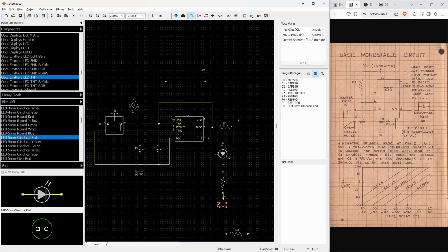So if I connect this to this, one interesting thing is if I click that, you can see they all highlight and it shows it with its net name ground. So that's important to tie those all together. I don't want this to just be a random other net, but actually connected to ground. So let's make the last connections here, going from out to the LED and the LED to its current limiting resistor.